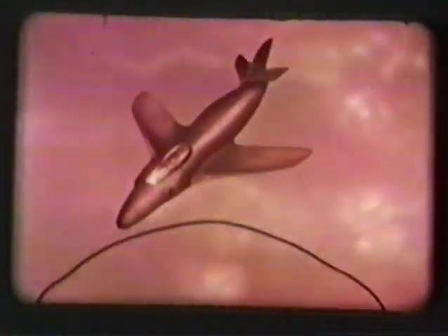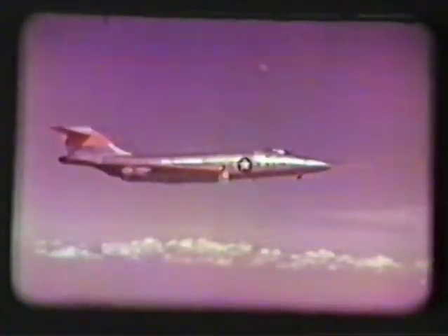This means the fuselage must have a waist to compensate for the wings and must flare out again behind. Above Mach 1, the bow wave adds its own drag. This can be reduced by having leading edges and nose sharp rather than rounded. Compare the effect on the bow wave of sharp and rounded leading edges.